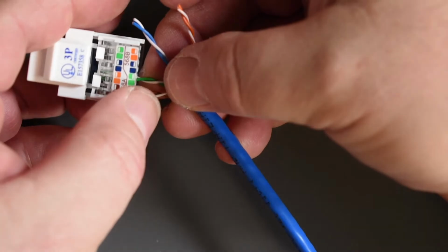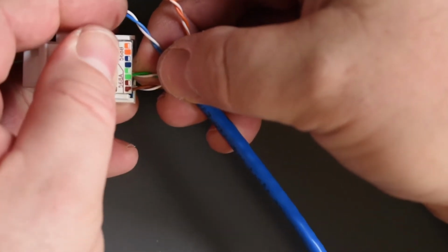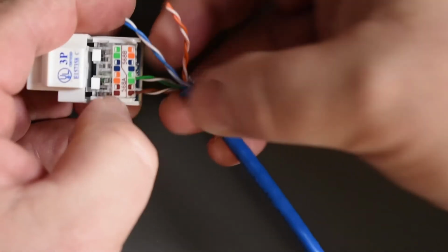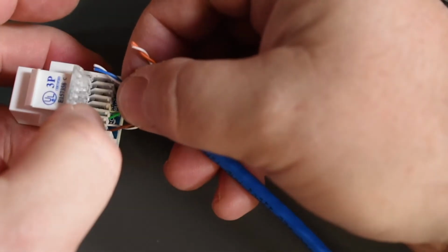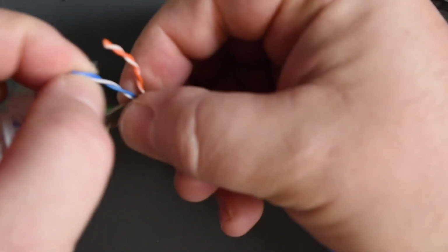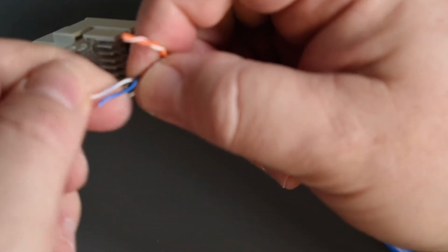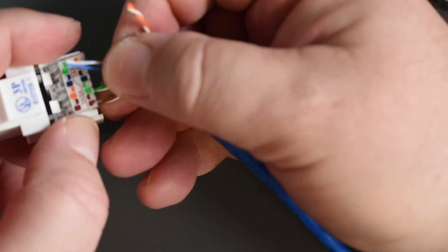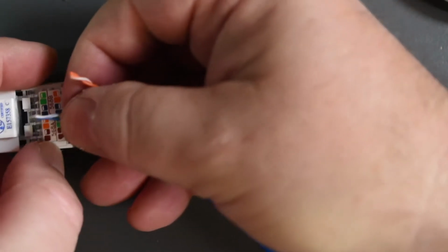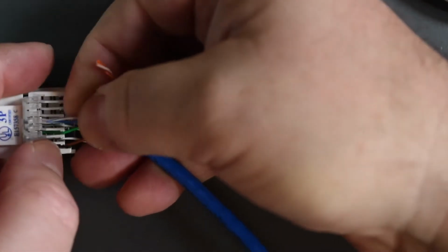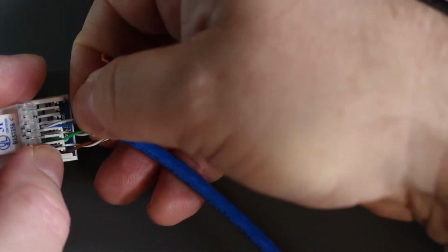Which is next? The blue, okay, because we're doing the B configuration, right? So insert, close and open. Insert, close and open. Insert, close and open until you're done. Okay, so blue. All right. Here again, I'm just going to twist this a little bit that way, and then untwist it that way. So we have the solid on this side and the stripe on the other side. Again, insert that into the grooves.